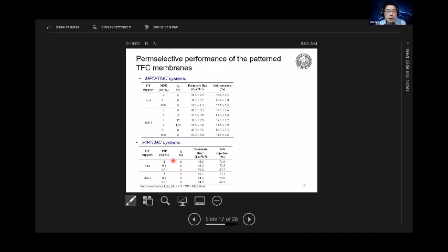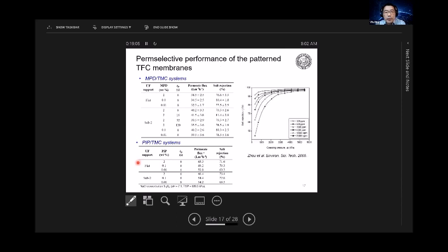All right, and for these TFC membranes, we used stirred cells at high pressure to look at their salt rejection performance. Their permeability is comparable with commercial RO membranes and NF membranes. The salt rejection looks a little bit low; it's about 70–80%. But this is a study where people looked at commercial membranes under different salt solutions and pressures, and it is very comparable. Okay.